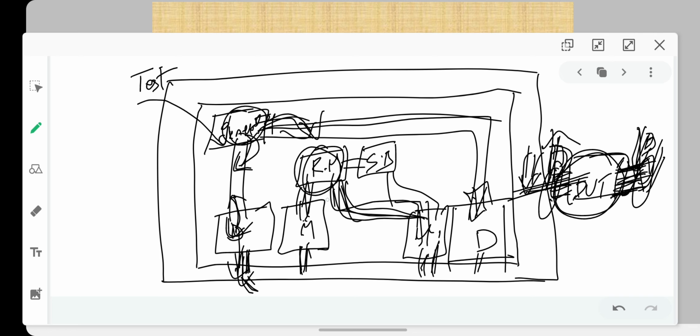From your reference model you're going to get some output, and from your DUT also you're going to get some output that is monitored, and this monitored data is given to the scoreboard as well. The scoreboard is the component that shows you whether the test case failed or not by comparing the two results from your reference model and the DUT. Your scoreboard compares both the outputs and gives the test pass or fail result.